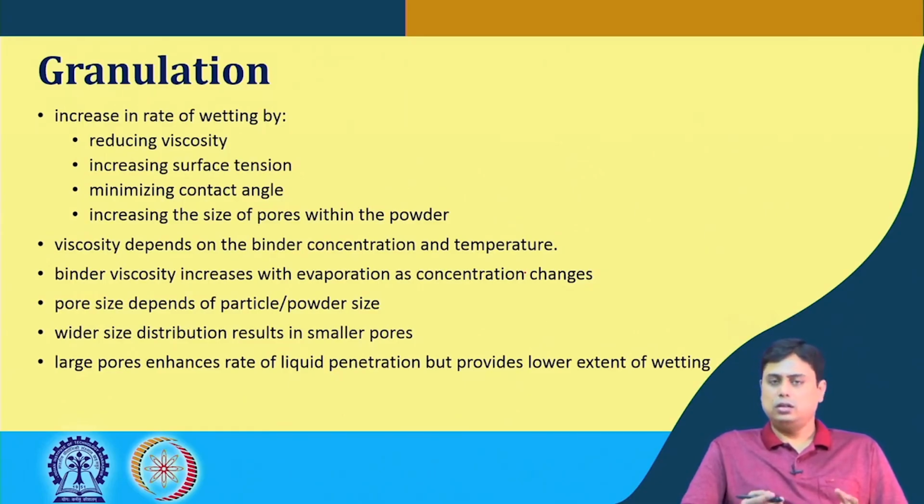Now, viscosity of this solvent depends on the binder concentration and the operating temperature. Now, it has been seen that with evaporation, binder viscosity increases because the concentration is changing, it is becoming more and more concentrated. So, the viscosity changes or increases during the evaporation step.